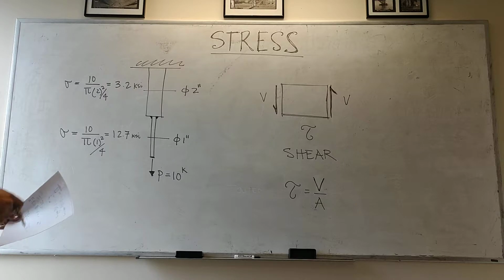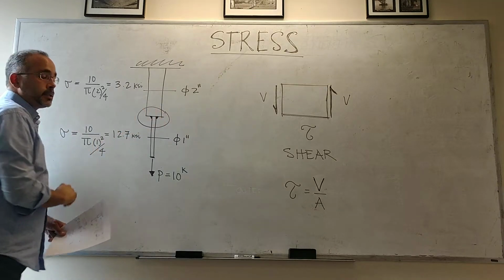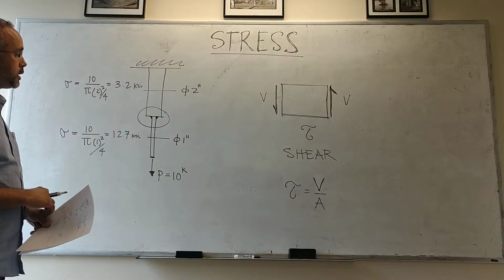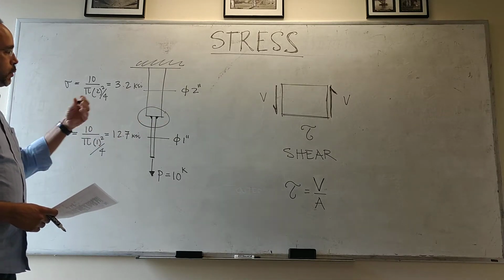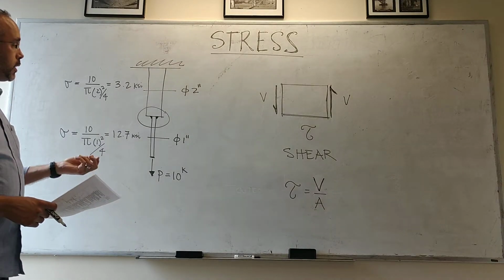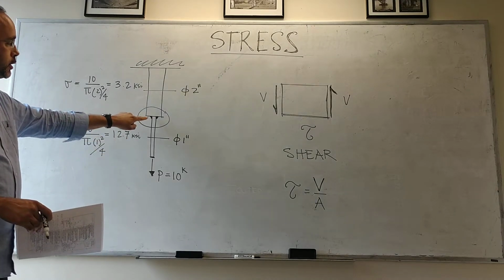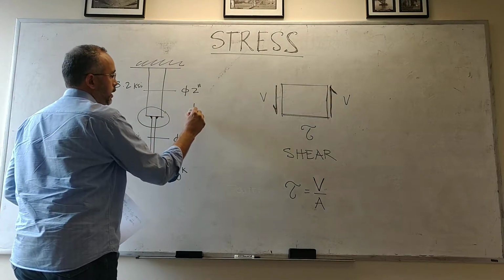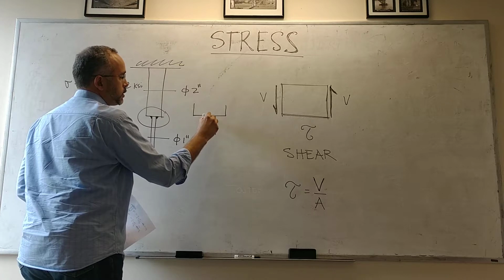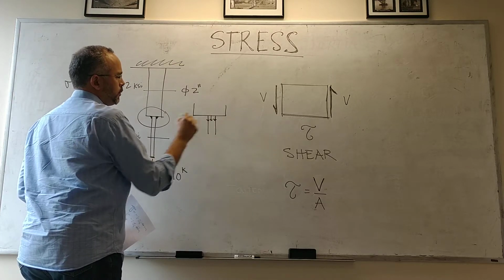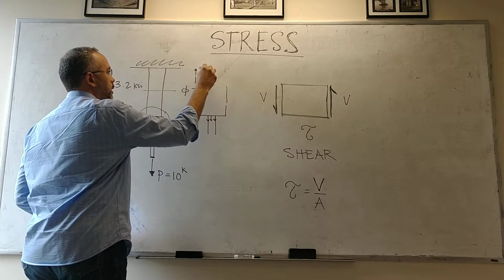Now, there are some stress concentration effects that take place at this connection. We're not going to discuss these at this point, but they're very important and they need to be considered. The way to calculate those is you can use theory of elasticity, or you can use finite element modeling to try to compute the stress concentrations around this point. The reason that it happens is because this stress is coming in here, and this one becomes uniform up here, right?